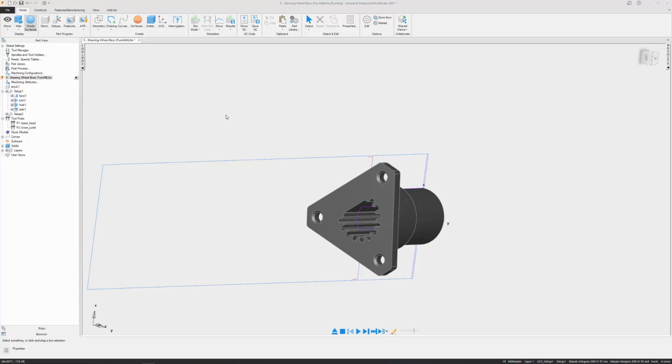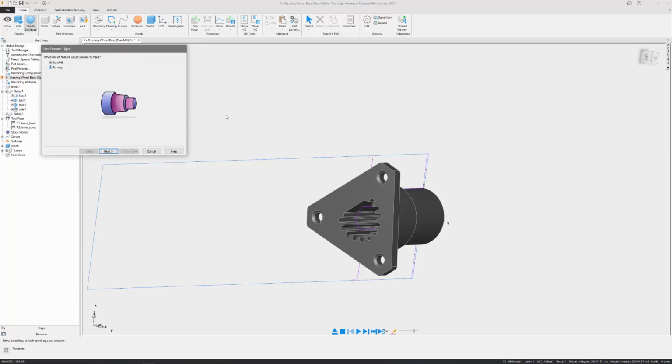There's a feature in FeatureCAM called a cutoff feature. It's going to make this particularly easy. It's going to be a turning feature because it will be our part rotating here, not live tooling. And we'll find cutoff in the from dimensions section. Now it's pulled the OD and the ID from the part. We'll leave those in the width. Those all look fine as default.